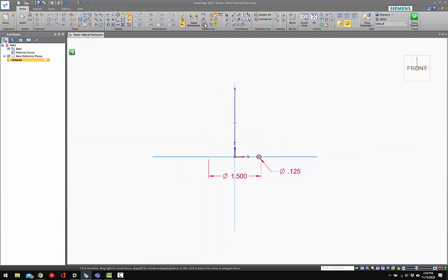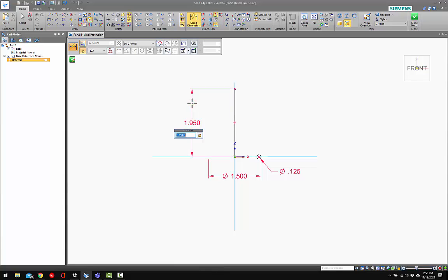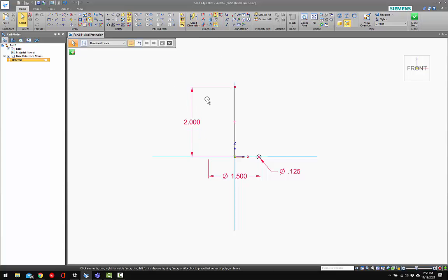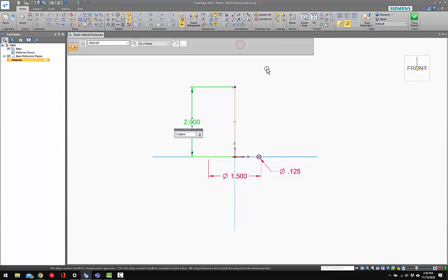All right. And then here, it's not only my axis of revolution, it's actually going to be something else as well, a parameter that will control our adjustable spring. So I'm going to make this, let's say, 2 inches. The other thing I'm going to do is rename this dimension and give it a name of spring underscore height, if I can spell. And in this name, you can't have any spaces. That's why I've got the underscore, and just click the green accept key.